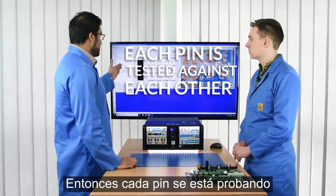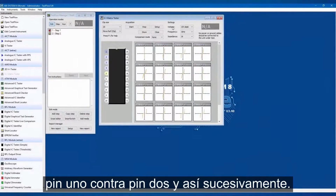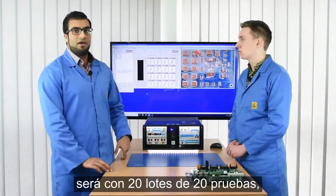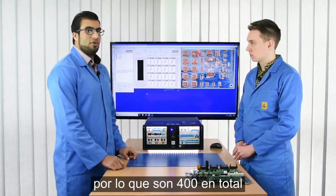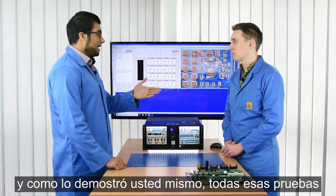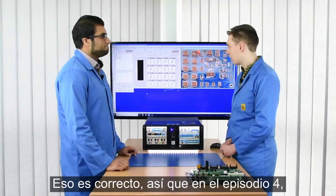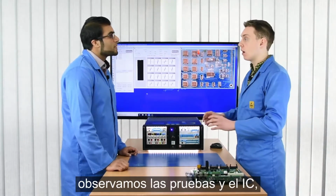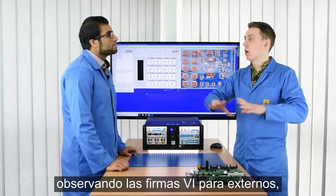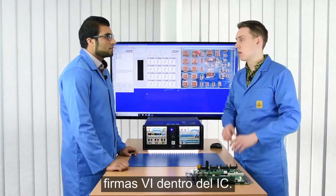So each pin is being tested against each other, pin 1 against pin 1, pin 1 against pin 2, and so on. For example, let's say we have a 20-pin device, maybe 20 lots of 20 tests, so 400 in total. And as demonstrated by itself, all those tests happen almost instantly. That's correct. So in episode 4, we looked at testing an IC, looking at the VI signatures from external to the IC to the ground. This time we're looking at VI signatures within the IC.